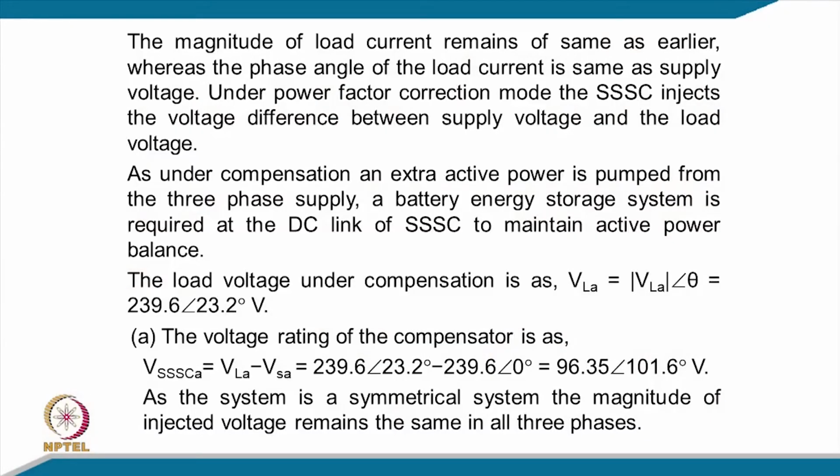So, the magnitude of the load current remains the same as earlier, whereas the phase angle of the load current is the same as the supply voltage. So, under power factor correction mode, the SSC injects the voltage difference between the supply voltage and the load voltage. As under compensation, extra active power is pumped from the single phase supply.